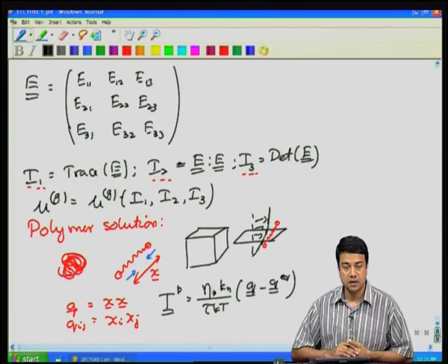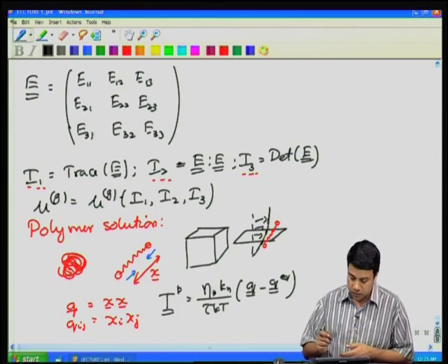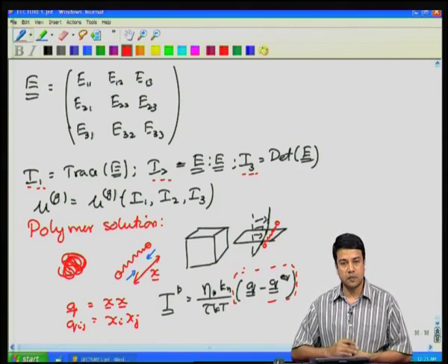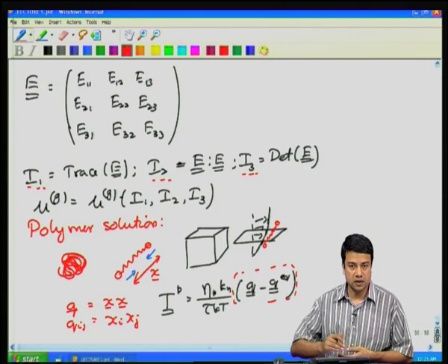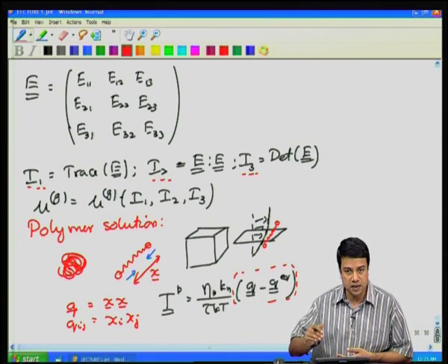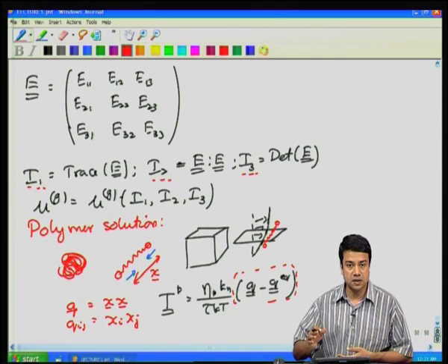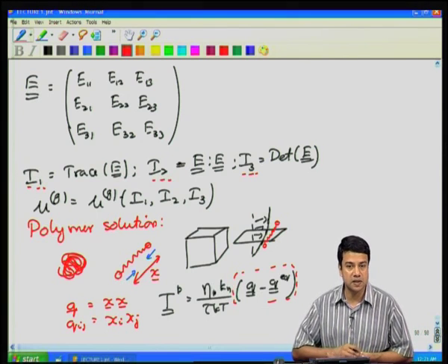Okay. So, in addition to writing equations for the fluid velocity, one will also have to write equations for this polymer conformation tensor, and couple these two, because the stress within the fluid does depend upon the stress that is transmitted by the polymer molecules themselves. So, in those cases it is necessary to write an additional conservation equation for this polymer stress tensor itself.